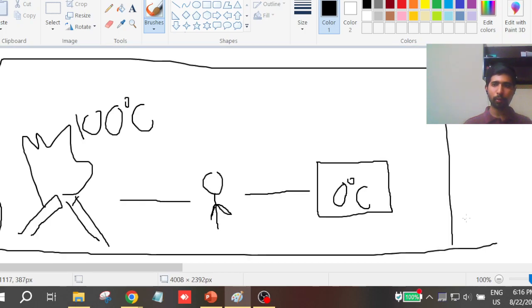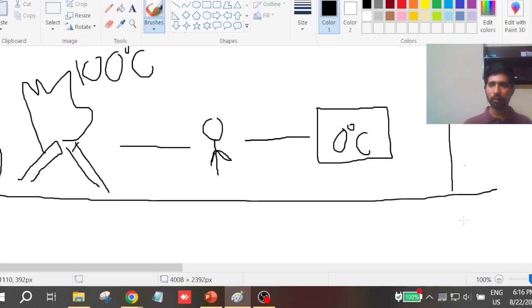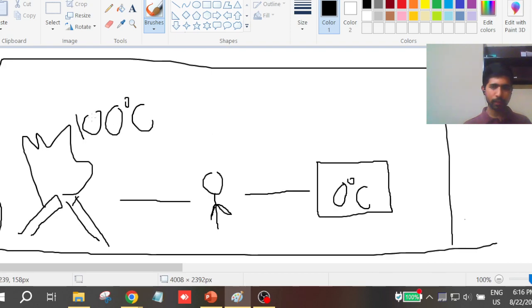So let us see what type of heat transfer will occur here. Will there be any convection here? What I am saying is that there is no airflow. So there won't be any convection, because convective heat transfer is mainly driven by the bulk motion of fluid particles, and that is not happening here because the air is stationary. It's only a pure diffusion process, or you can say conduction. For the energy equation it's conduction, or in general we call it diffusion.